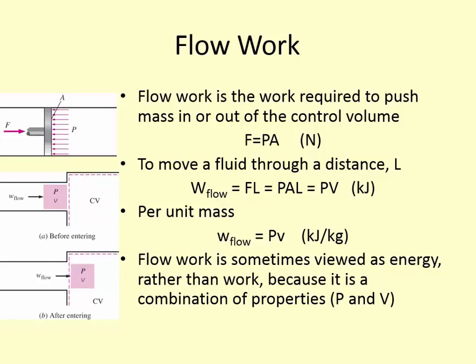So sometimes we look at flow work as actually an energy term rather than a work term because it's a combination of two property values. So sometimes rather than looking at it as a work, like a force through a distance, we think, well, it's actually more like energy because it's inherent to the fluid itself that it's this pressure times volume.